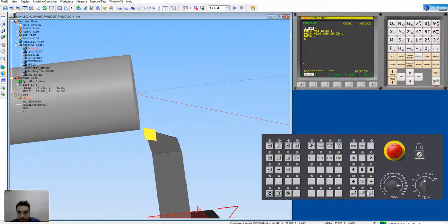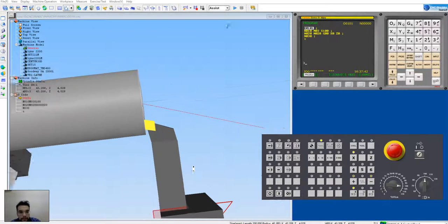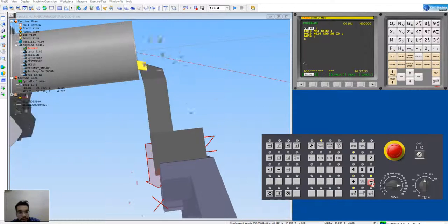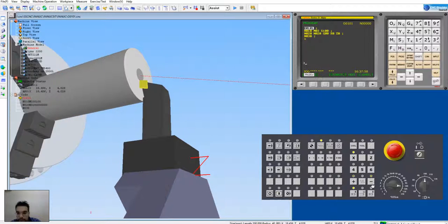Approach it, and apparently we cut into it a little. I'm going to scratch this so my surface and workpiece 0 reference would be exactly the point I'm scratching it at. So let's go ahead and scratch it till the middle. If you can see this, it actually reddens or highlights itself as I'm approaching, so it shows that I'm touching the workpiece. I'm going to make it 0.